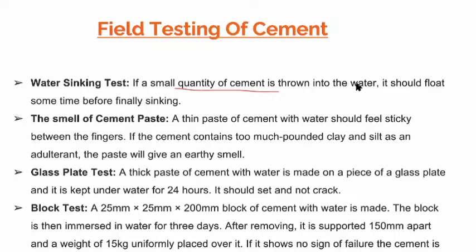The smell of cement paste. A thin paste of cement with water should feel sticky between the fingers. And if the cement contains too much clay and silt as an adulterant, it will give an earthy smell, that is the smell of soil.